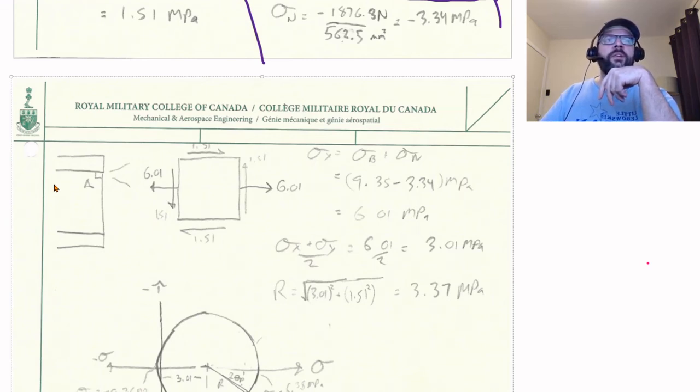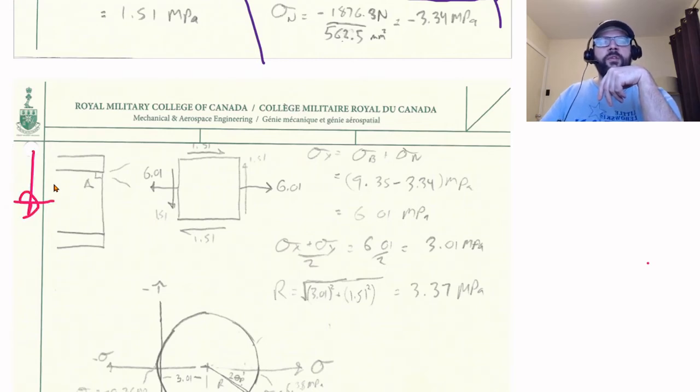We know that on this end of the beam, we got a load that's pushing downwards. So that'll continue on until we hit this cube here. So that means on this face, the shear load is going to be pushing downwards, which means that on this face, the shear load will be pushing upwards. And obviously, those two need to be in that direction as well.